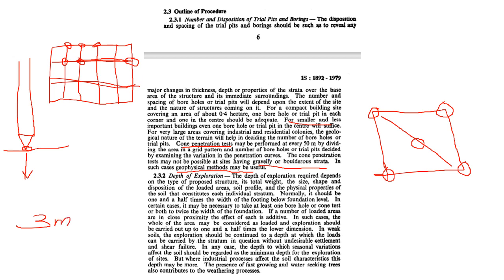okay. That is ideally you should take the boreholes up to the hard stratum that is existing at that particular site or up to the bedrock. Then once you find the bedrock, do not stop your boring there, because in some areas or in some cases this bedrock that you observed at the end of one borehole may be just a big boulder, okay, or a big piece of rock that is existing, but it may not be a complete extension of one rock, okay.